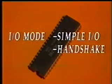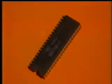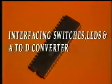Under IO mode, simple input-output interfacing as well as handshake data transfer is possible. Bit set reset mode is good for manipulating individual bits of data. We have also learnt simple application like interfacing switches and LEDs, and also a complex application like interfacing an A to D converter.